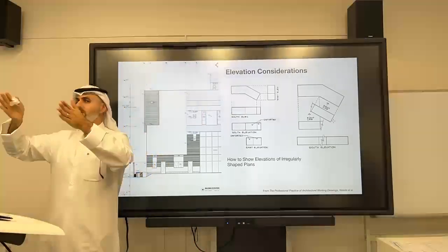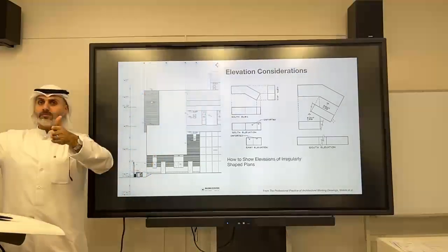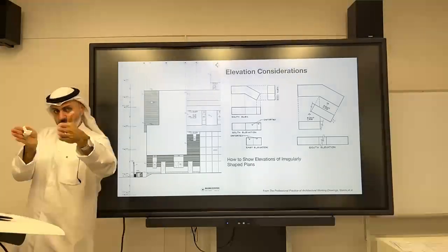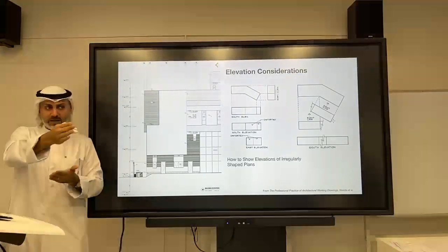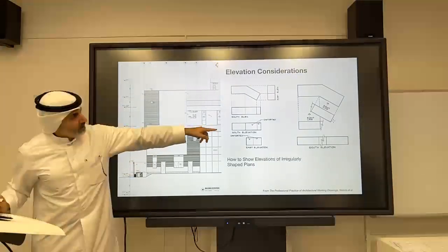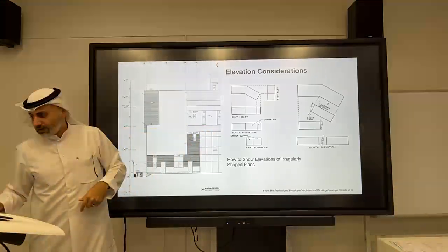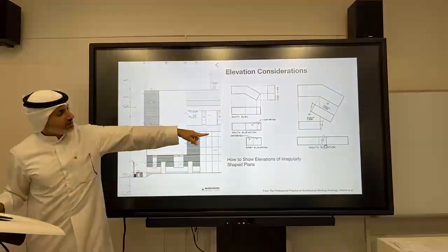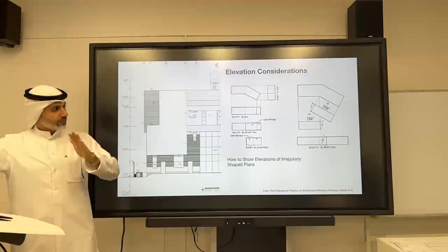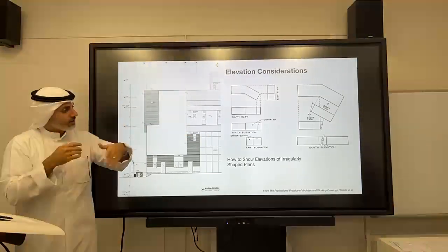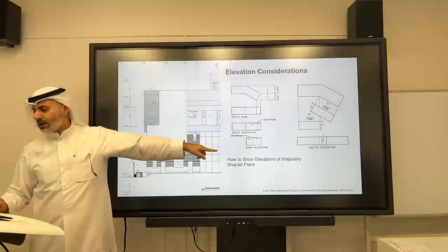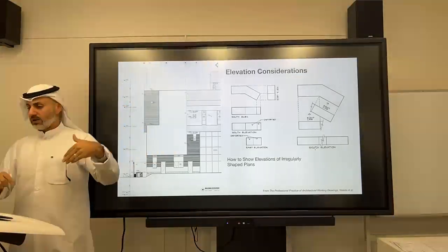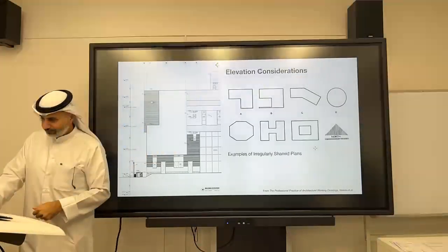So when you look at the elevation, the meter shows less than a meter, say 90 centimeters, because it's at an angle. So you can see that in this example. And when you draw it, you can show this break, like we draw the break in the stairs, and then you're breaking between two elevations, two angles. And then you can show both as straight without distortions.